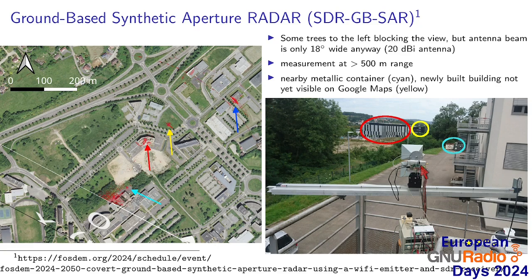In any case, the SDR stream must never stop, otherwise the phase condition between transmitter and receiver might be lost, so we never want to miss a single sample, continuously recording and streaming, and yet we need to only collect the data when the antennas are stable.